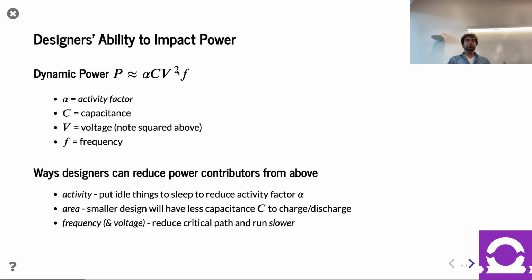And so you might say, okay, well, why would you do this? Well, because the other one's running at half frequency, you can turn down the voltage. Because it's quadratic, you maybe could even halve the voltage, which means each one takes a quarter. 2 times a quarter is a half. So in other words, you've halved the raw power consumption for the same throughput. So you've traded area for power in this case, right?